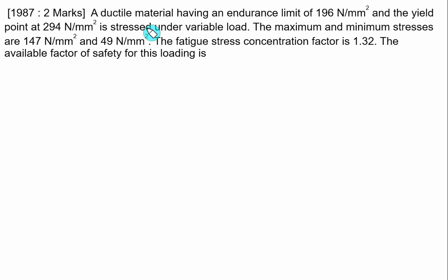A ductile material having an endurance limit of 196 megapascal, yield point SYT is 294 Newton per mm square, is under variable load. The maximum and the minimum stresses, that is sigma max and sigma minimum, are 147 and 49. Fatigue stress concentration factor is given as 1.32, which is to be applied only to the alternating stresses. The available factor of safety for this loading we have to calculate.